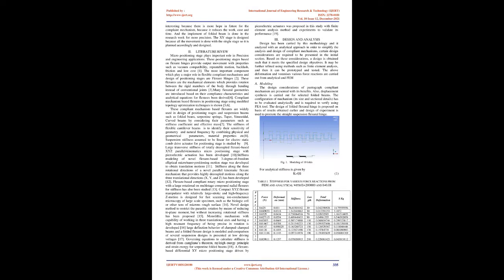2. These flexures are the mechanical elements which provide rotation between the rigid members of the body through bending instead of conventional joints. 3. Many flexural geometries are introduced based on their compliance characteristics, and analytical equations for flexures have been derived for compliant mechanism-based flexures in positioning stages using modified topology optimization techniques. 5,6. These compliant mechanism-based flexures are widely used in design of positioning stages and suspension beams such as folded beam, serpentine springs, taper, sinusoidal, curved beams by considering their parameters such as stiffness coefficient and effective mass. 7.